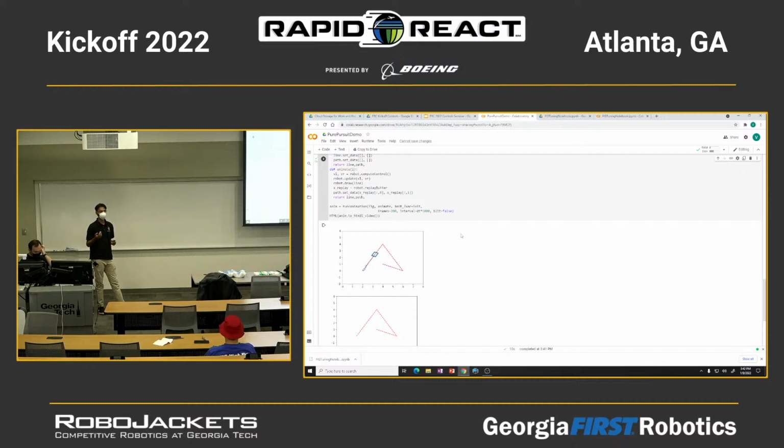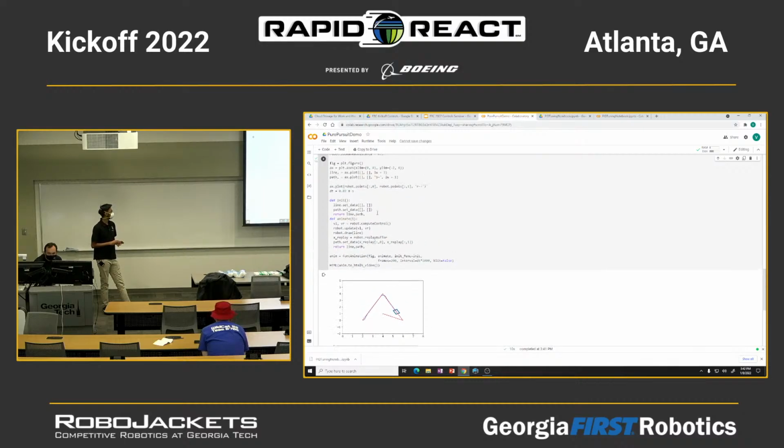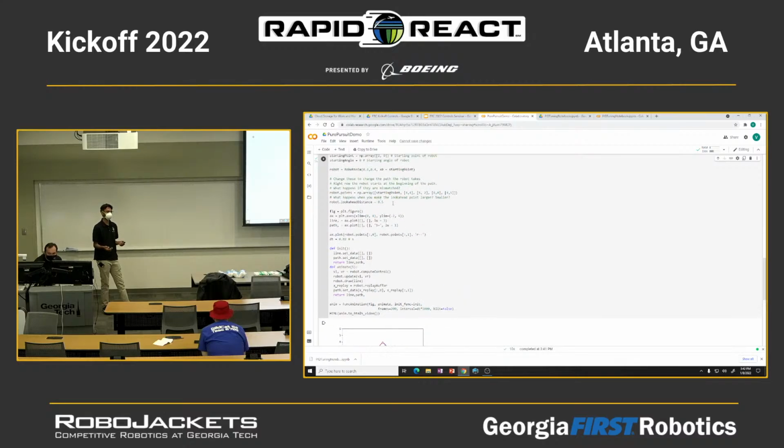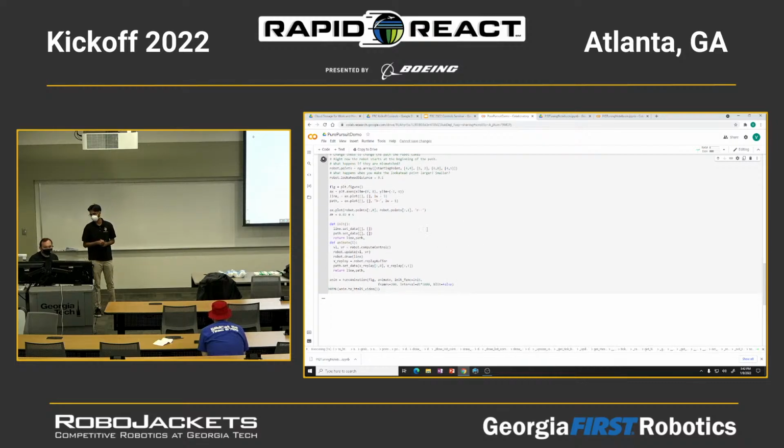And of course, a look-ahead distance of 0 is essentially the same as point-to-point motion, because you have to make an infinitely tight turn at the end, which requires you to stop completely. So the look-ahead distance lets you choose between doing this in a point-to-point style, or with a big arc traveling all the way around. As you tune that value higher or lower, you'll see how that trade-off plays out in your robot. It actually breaks when it's too low.